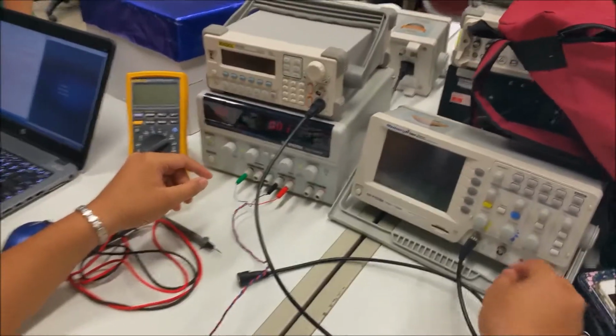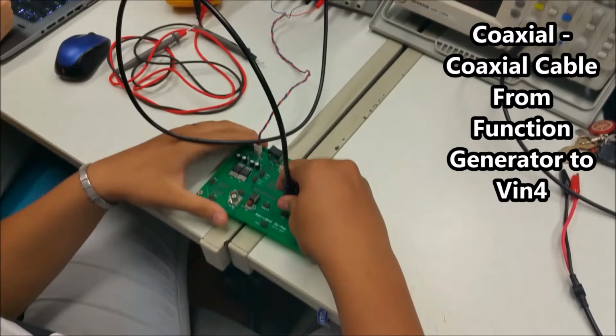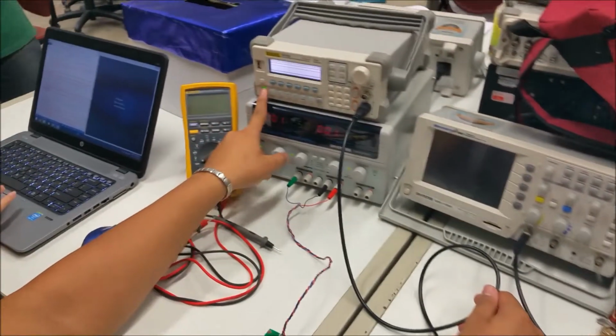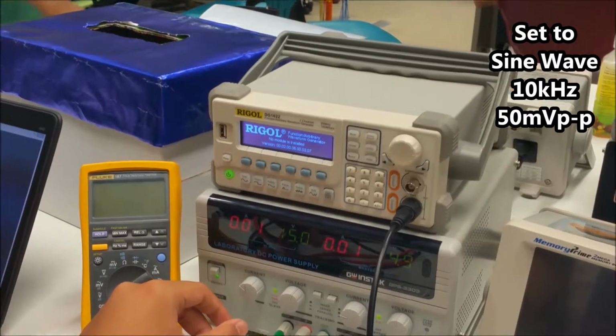We will need one coaxial cable. Connect one end of the coaxial cable to the function generator and the other end to VIN4 on the circuit board. Now turn on the function generator. We will be using the sine wave for the measurement.